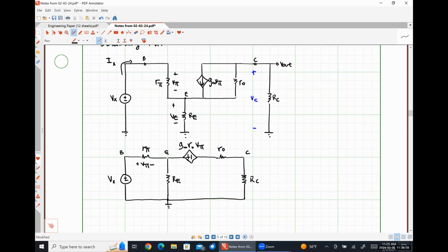Okay. So before we start our analysis here, does anybody have any problem with how we got from our normal small signal model on top to this representation down here? Anything seem suspicious? Hopefully it all seems okay, because as best as I can tell, it's correct. Okay. So ultimately, we are still trying to just find the ratio of this voltage Vx to whatever current is leaving the positive polarity terminal. So it looks like effectively I did mesh.